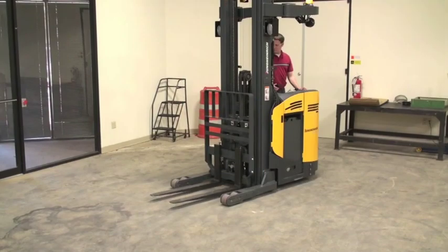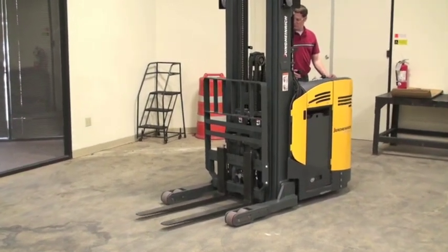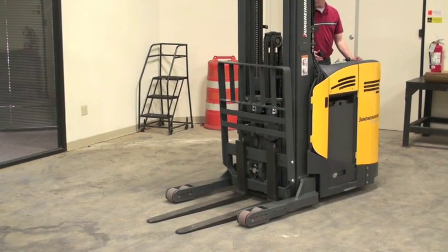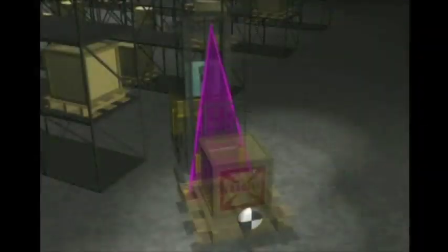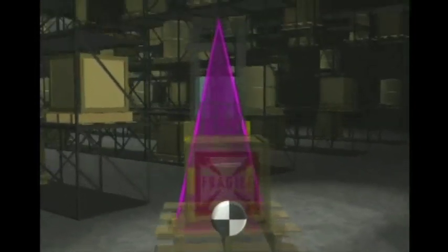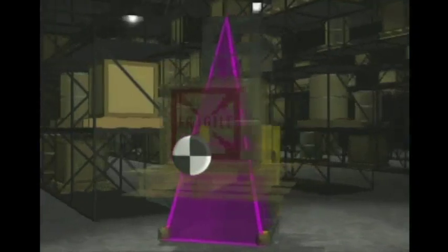Sometimes, lift trucks are equipped with attachments other than forks. Attachments such as clamps or side shifters actually reduce capacity in two ways. First, the attachment can often lengthen the load center, thus reducing its load lifting ability. Second, the attachment's own weight reduces the lift truck's capacity. You should therefore think of a truck with an attachment as already partially loaded.